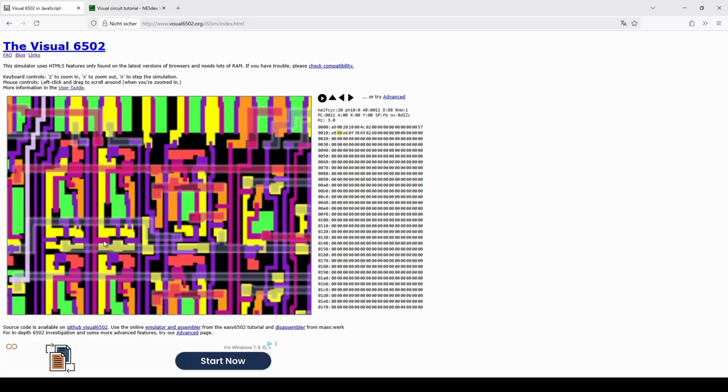You can see here, this enables the x onto SB line, which now lets the value currently stored in x go onto the bus. And then it's going to go to the ALU to be incremented. So we'll simply step this. Nothing happens yet.